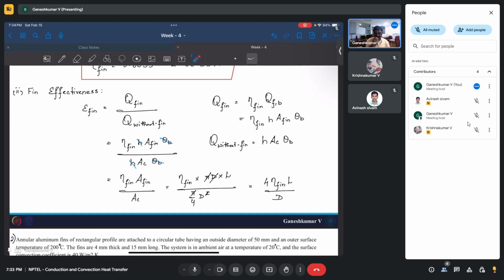That is going to be sure, for sure, right? So now just because adding the area doesn't necessarily mean you have higher heat transfer. You also have something called efficiency of fin, which is also a parameter, which is a function of thermal conductivity of the fin material. So you have to take both of these into account. That's what I'm trying to say.